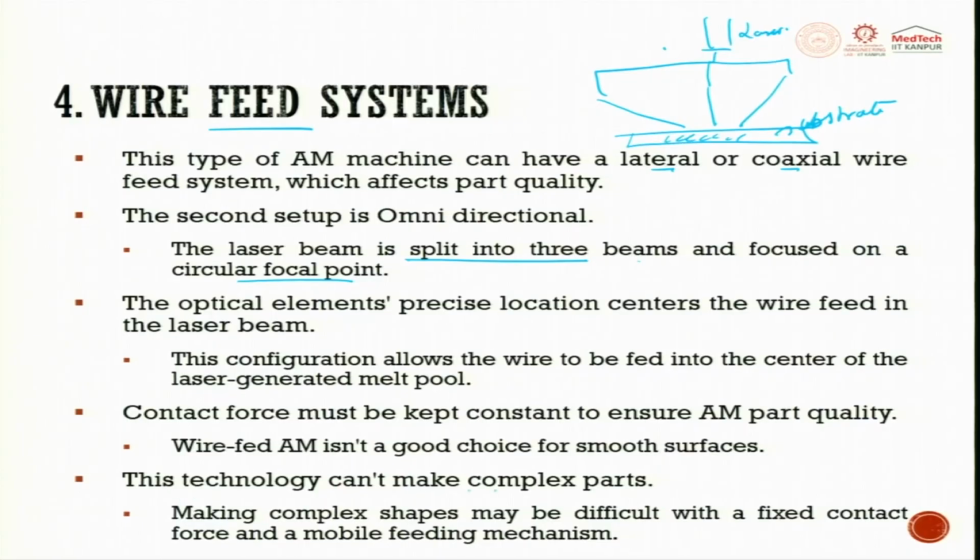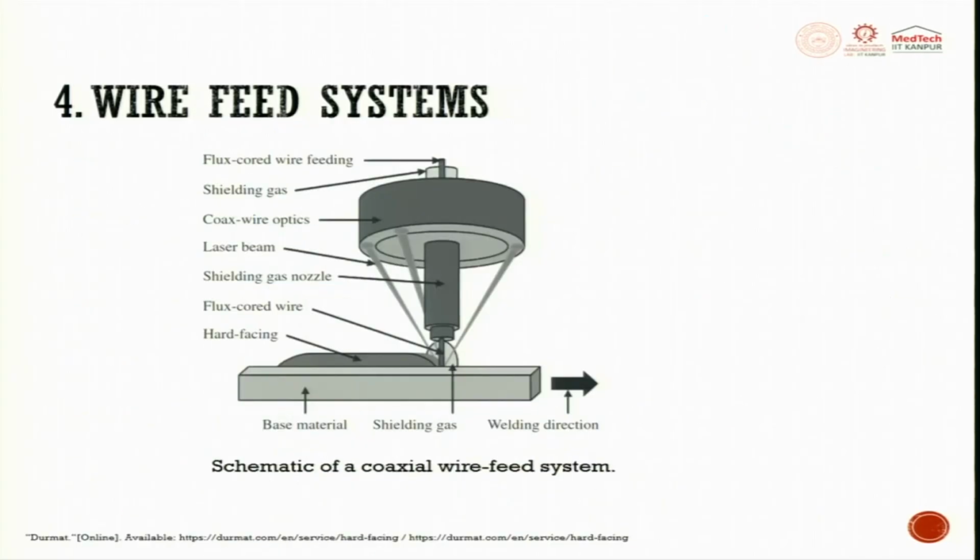This technology cannot make complex parts with respect to wire frame, because the wire itself, when it gets melted, will not be very small particles, it will be a large droplet. So, complex parts cannot be made through this.